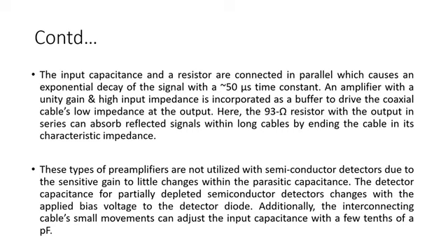This type of preamplifier is utilized with semiconductor detectors due to its high sensitivity of gain to little changes in the parasitic capacitance. Even a minute change in the parasitic capacitance causes a very big change in the gain. The detector capacitance for partially depleted semiconductor detectors changes with the applied bias voltage to the detector diode.